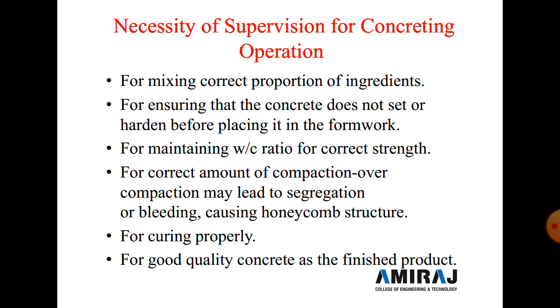Next is the necessity of supervision for a concrete operation. Here, the necessity is for mixing the concrete ingredients in proportion, for ensuring the concrete does not set or harden before placing in the formwork, and for maintaining the WC ratio. So what is the WC ratio? It is the water cement ratio, for getting the correct strength.